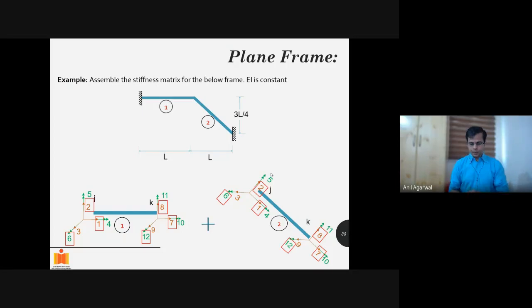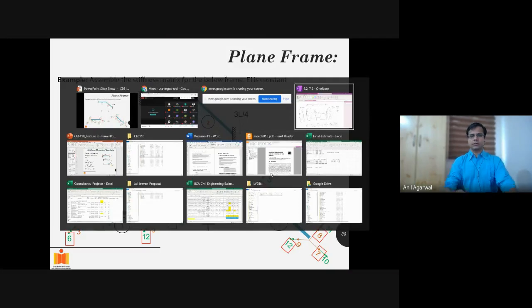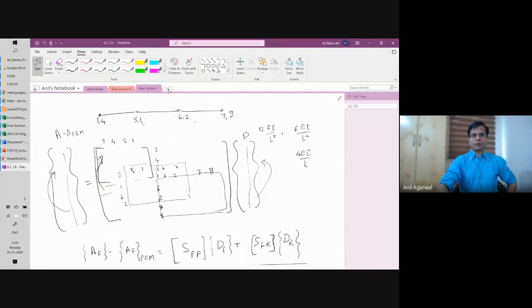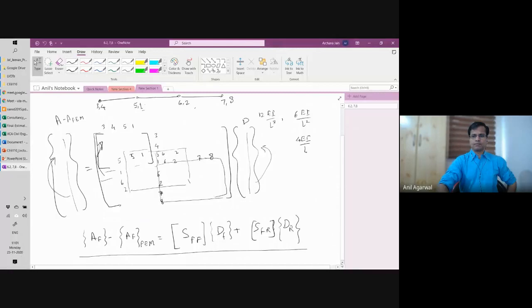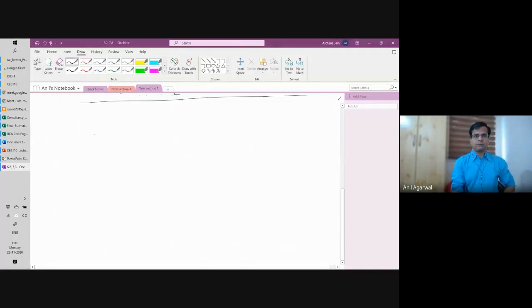Fine. So far, all the problems that we had done were regarding plane beams, right? If you are dealing with a plane beam problem, a plane beam is typically restricted to move only in the perpendicular direction. So movement in this direction and a rotation in this direction, or to keep it positive sign in this direction. Only these movements are allowed. Axial deformations are not allowed. And that's why when we deal with plane beams, we only go in a single direction.